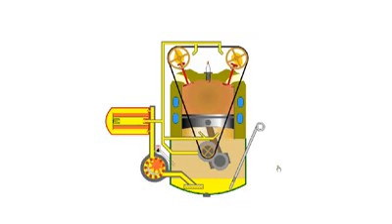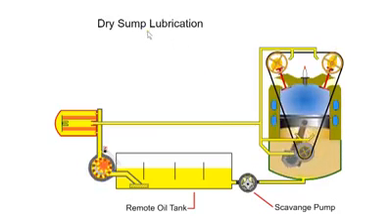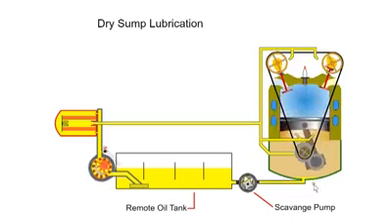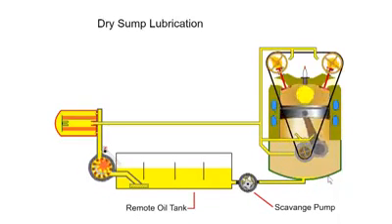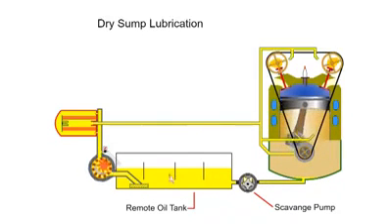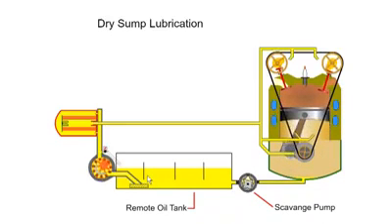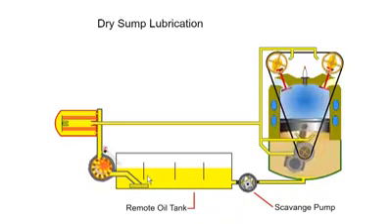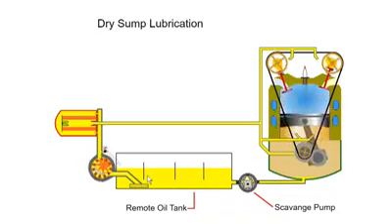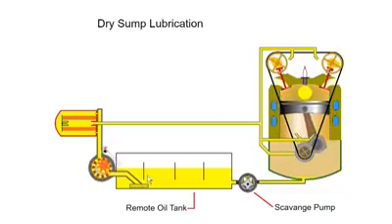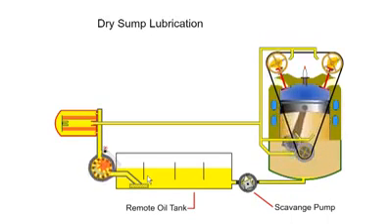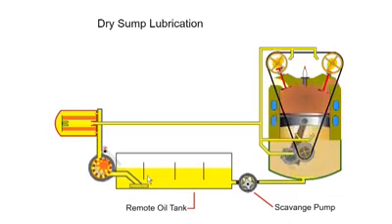Some cars, such as high-performance cars, have a dry sump which has an external reservoir which is not located under the engine. The engine can be moved down, providing a lower centre of gravity. Oil is kept away from the rotating crankshaft, and the sump itself can be any shape or size. An additional oil cooler can be used which operates similar to the water cooling radiator and prevents the oil from overheating. On modern cars, electronic analog measurements are used to monitor oil pressure and level. Oil quality can also be monitored, and the engine control unit alerts the driver when an oil change is due.